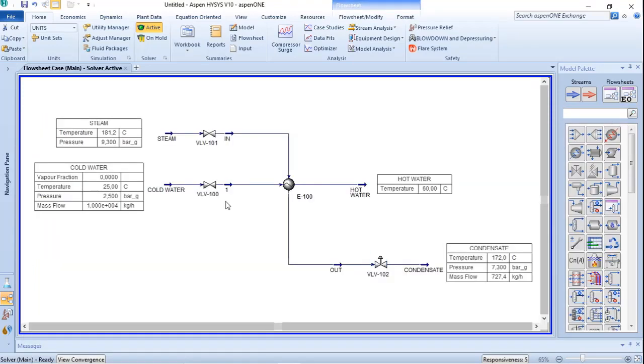This way we are working with theoretical valves. That is not the best way to do that, because when you are doing a dynamic simulation, you want to have the most accurate results compared to the field application. So what best fits for dynamic mode is getting the field information.